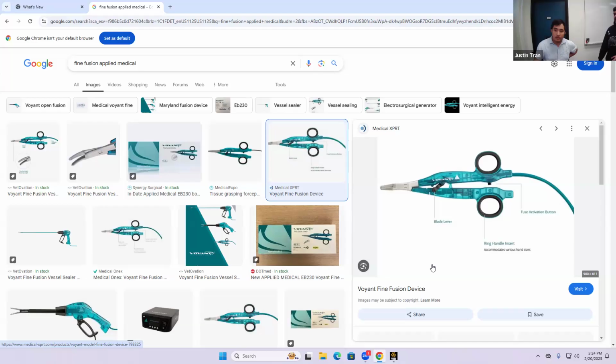With ANSYS, let's say we are applying the force. It's going to have a moment, which is going to be creating the force right here. With ANSYS, the way I would do it, I would actually change the CAD geometry so that there would be an object here, like a small object. Then you would apply a force here, and then you can compute the reaction forces on that object, as well as the deformation of the object. Or you can just compute the reaction forces, and that'll tell you how much force, in this case, mechanical advantage.